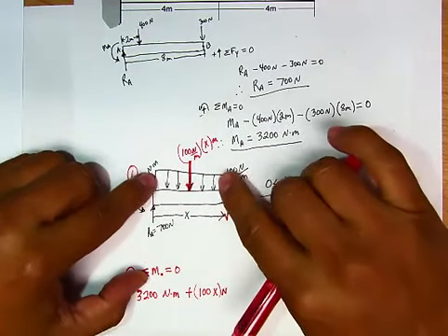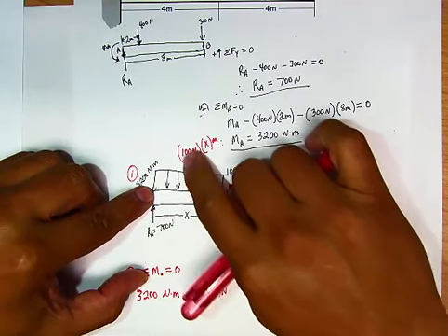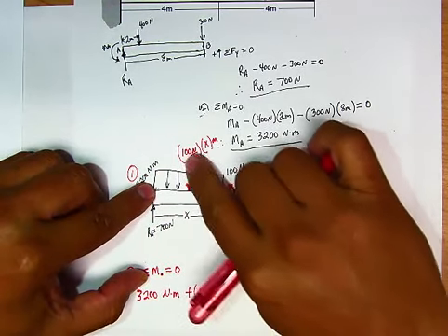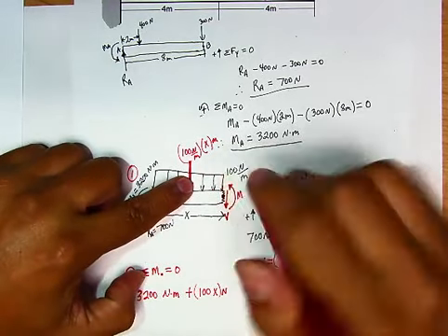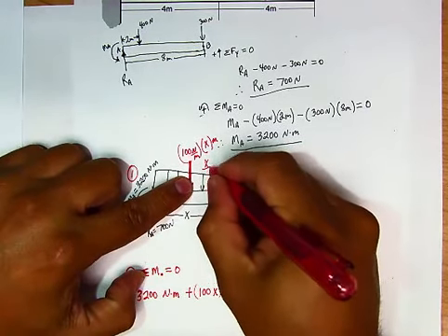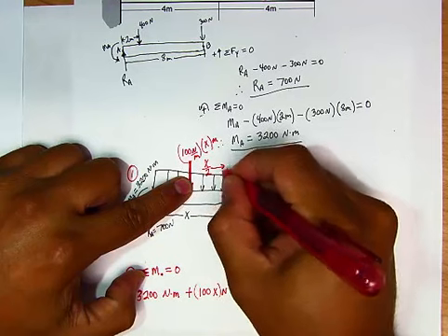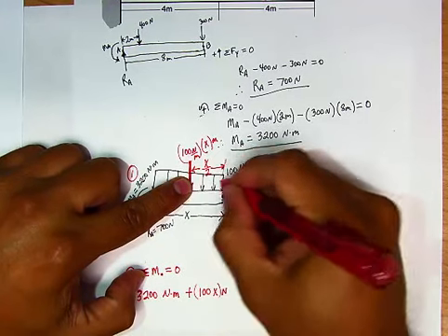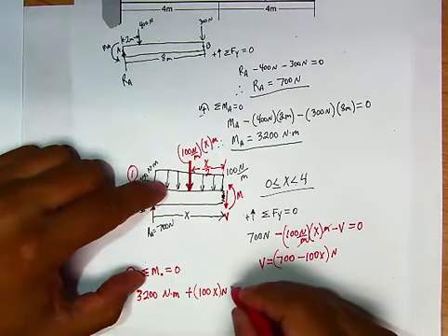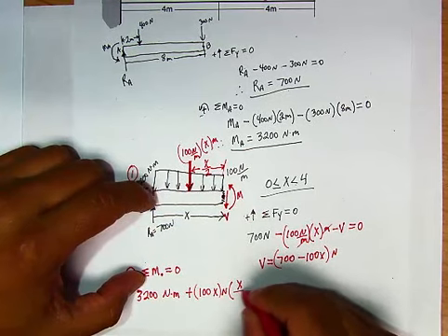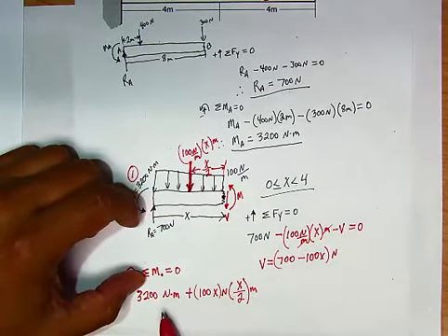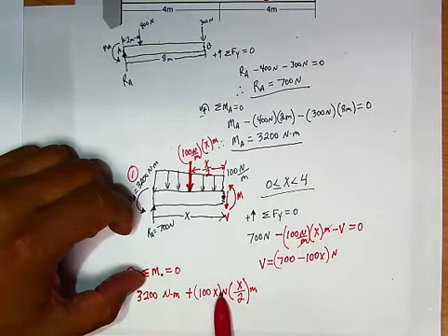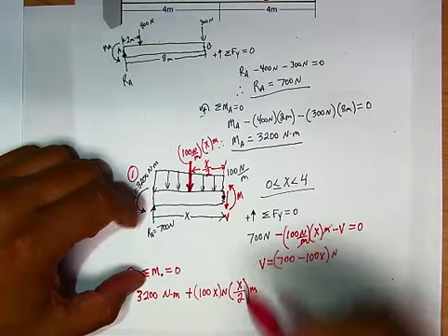So we need to find out what this distance is. Well, this distributed load is a rectangle. It is applied in the center of the rectangle, or the middle. If this distance is x, that means that this distance right here is x over 2. And that is the distance that we're interested in. So we multiply times that distance, x divided by 2 meters. So as you can see, our units are Newton meters and Newton meters.